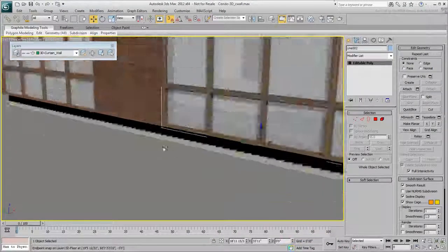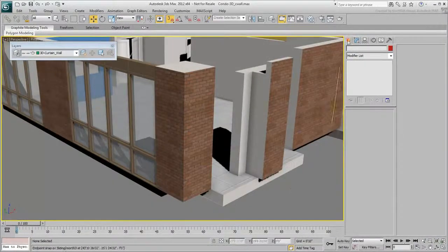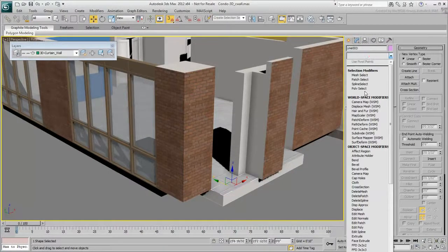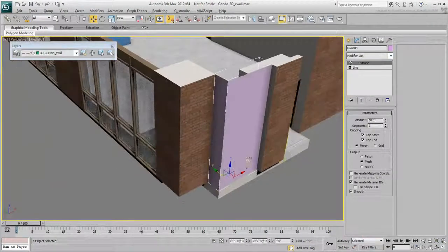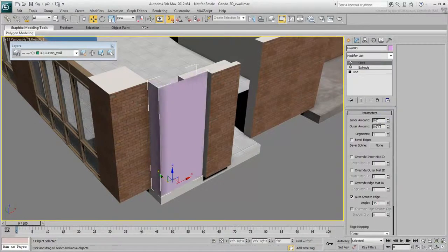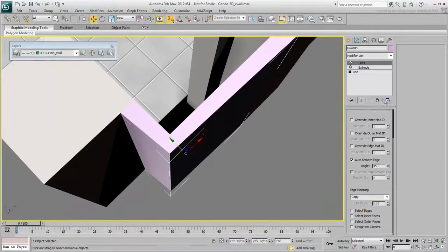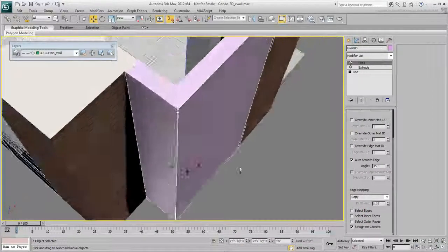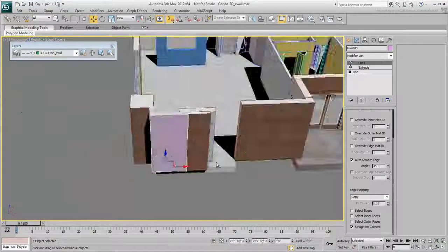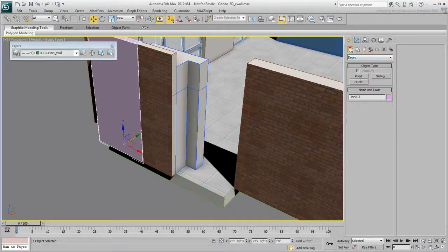For the L-shaped curtain wall sections, you could use the same technique, starting with a line. Extrude the line 10 feet up to match the height of the exterior wall, and then adding a shell modifier and adjusting its values. Be careful to always use the straighten corners option to avoid deformations. However, you will need further modeling adjustments and cuts to accommodate the corner mullions. Instead, try using the AEC Extended Wall tool as a base.